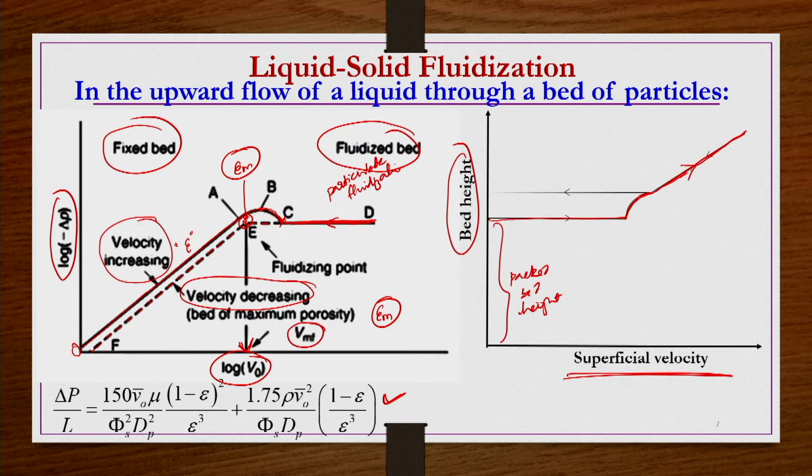Okay. Now, you fluidize it sufficiently, you can see the fluidized conditions, a proper fluidized condition, not just expanded or minimum fluidized conditions. After reaching that sufficiently high fluidized condition, you decrease the velocity.